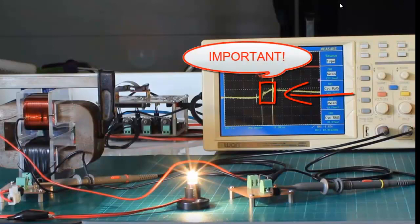slightly higher voltage. And always load your machine. Always, always load your machine. You have to have a load to be able to see what's going on, because remember, it's the currents themselves that actually make this work. The interaction of currents that are switched through the coils at a particular time is what makes this work. So you must have a load at all times, and if a load blows, change it straight away. Stick another light in, so have plenty of lights on standby.